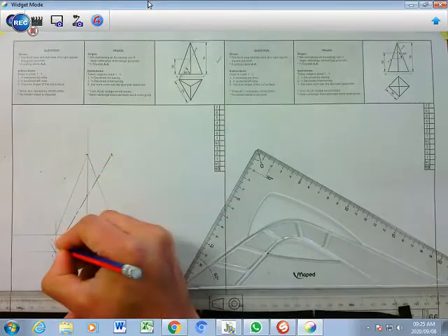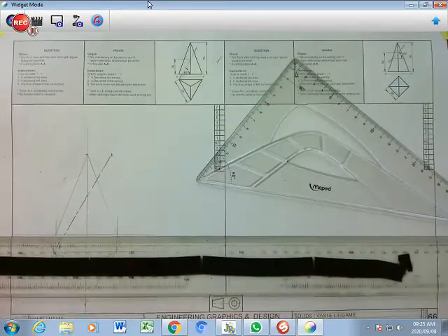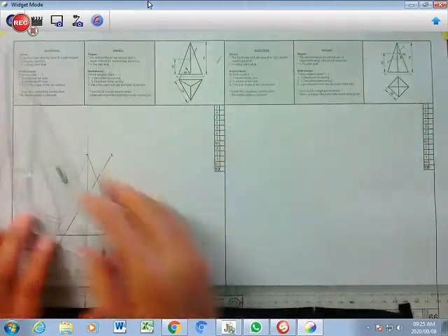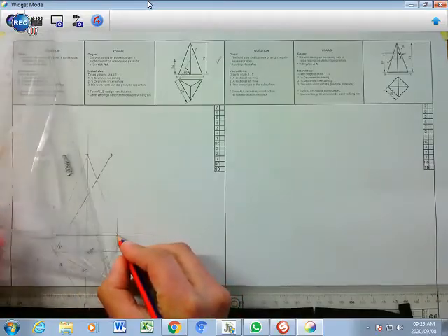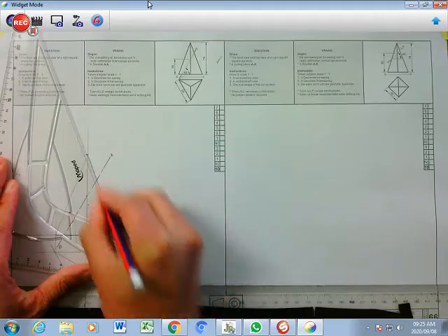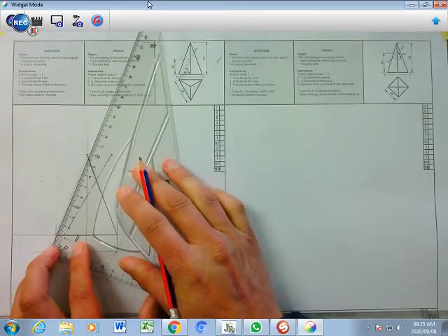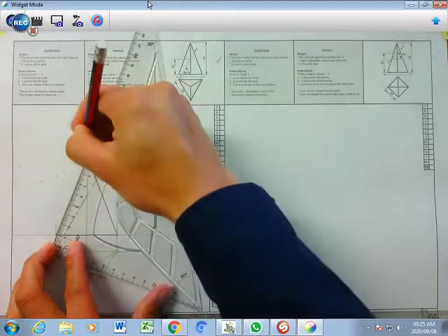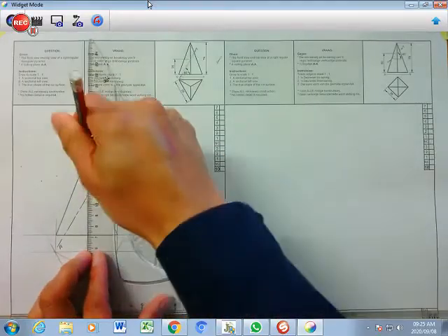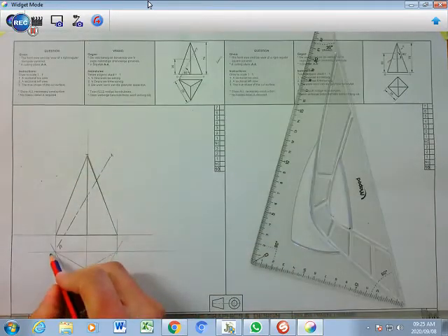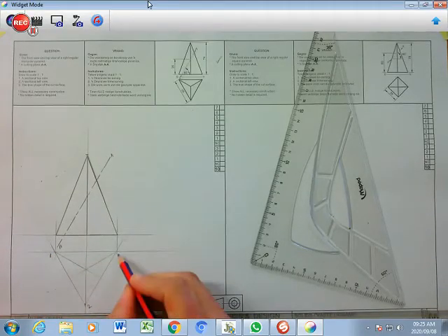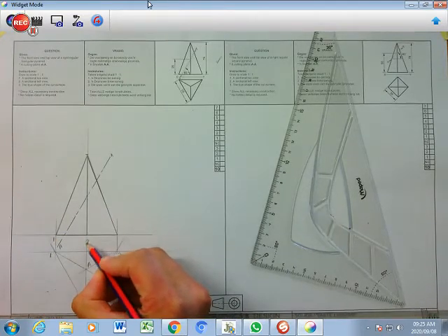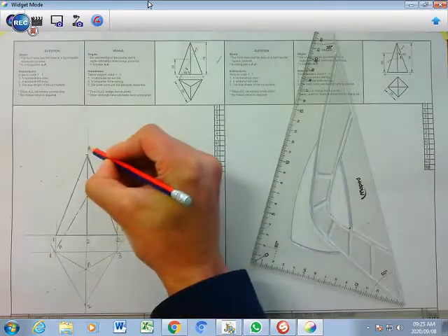I'm going to write the A, and I'm going to darken my front view where my cutting line is in. So that view has no problem becoming dark immediately, because there are no alterations that will take place in that specific view. So darken, it goes like that, and then straight down. So what I'm going to do is label it as number 1, number 2, number 3, and that's going to be A for apex. That's number 1, that's number 2, that's number 3, and that's apex there.